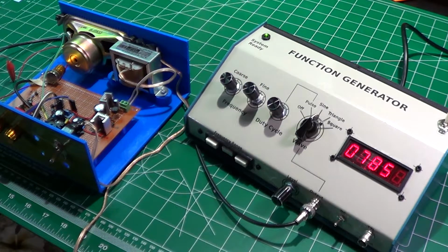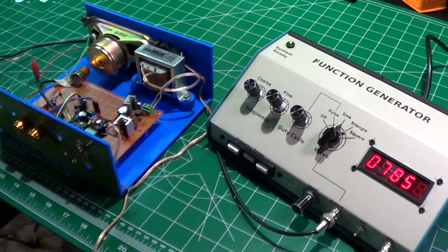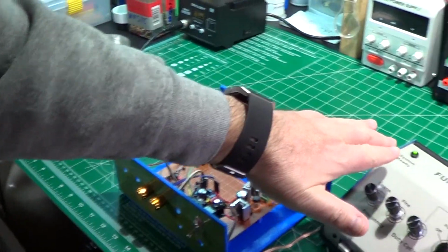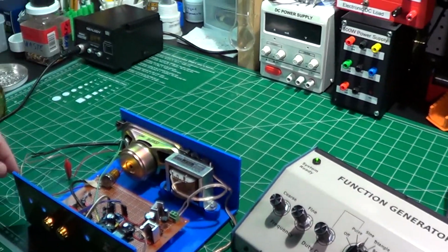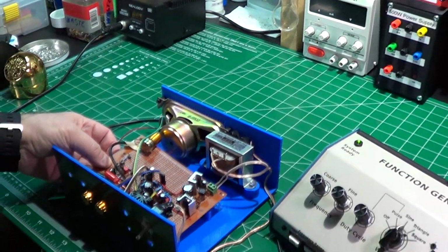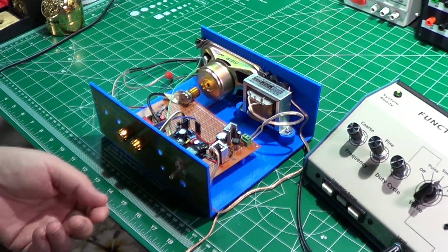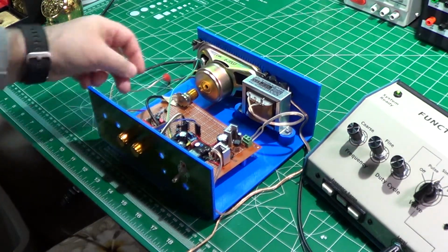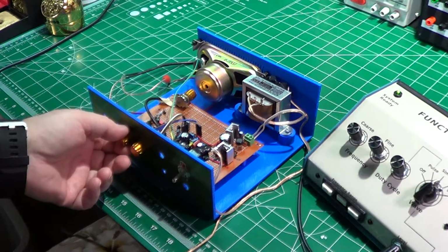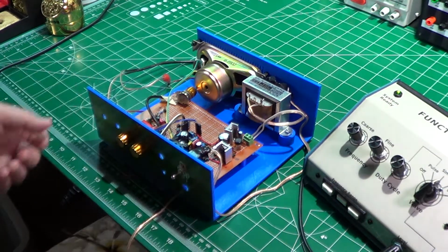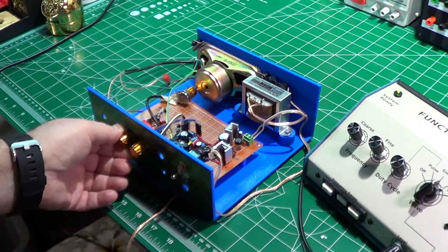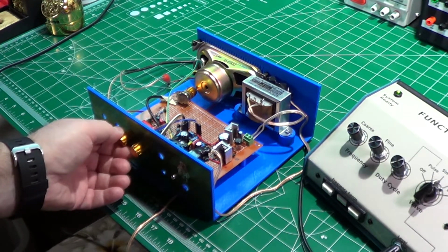I will now do a qualitative test of the preamp. To do that, I will need my function generator connected to the input of the preamp, in particular at the trim-pot RV1. The function generator is set to provide a sinusoidal wave. Let's start by checking the volume control to make sure that we can increase and decrease the volume of the sound emitted by the chain of the preamp and the power amp. I will just turn on the system. And now you can see that I can control the volume up and down.